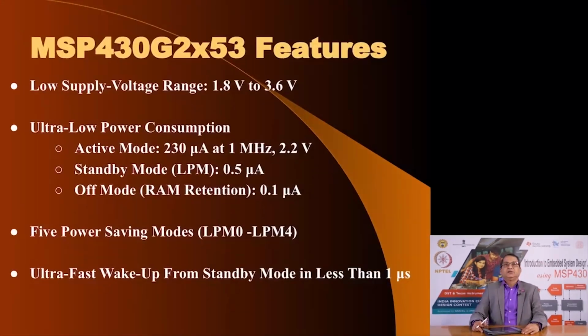These are the features. The supply voltage, unlike the microcontrollers of the previous era, which would operate at a standard 5 volts. You may also remember that TTL ICs, transistor logic ICs, operated at 5 volts, but as the frequency of operation increased, continuing to use a higher supply voltage led to higher power dissipation, and one way to reduce power dissipation would be to reduce the supply voltage.